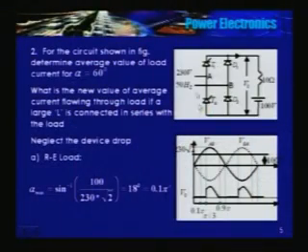Let me solve another problem. A half controlled bridge, two thyristors in one leg, load is RE. The moment I say the load is RE, the first thing that should come to your mind is that the load current is discontinuous. RE load is invariably discontinuous.